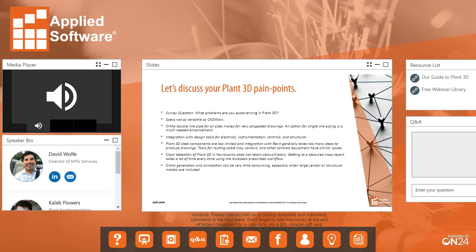That's all done in the ISO config style. So you can add whatever properties you want. You can add the equipment tag, you could add the nozzle pressure, size, any nozzle property really. So hopefully that's what he's looking for. The data and everything that you need is there. It's just configuring an ISO style to display what you want to see. Hopefully that answers the question.